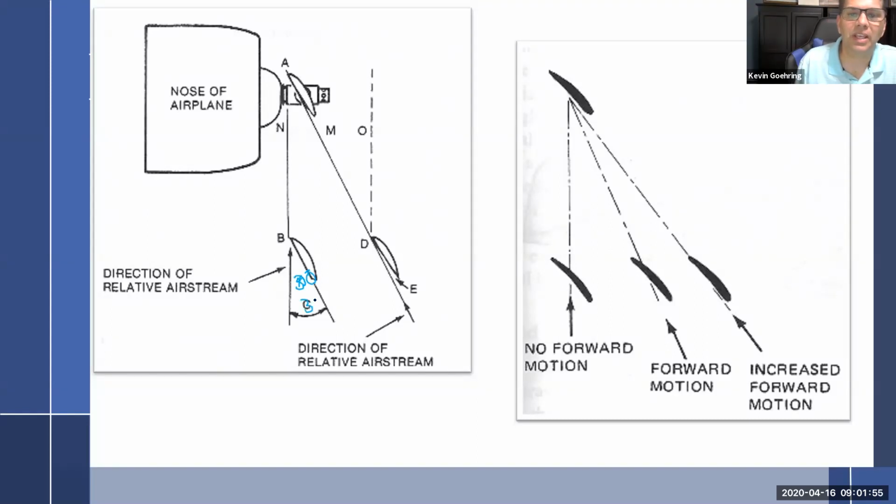So 30 degrees. How is that going to work when I'm supposed to have 2 to 4 degrees? So I've got a stall here. This is just stalling. It's not doing anything. So it's like a big paddle in the air that's not doing anything. It's just whacking the air and slowing the engine down, which is why you have the slow RPM when you get into this static RPM, which is what this is, static RPM. No thrust, just a paddle whack in the air.